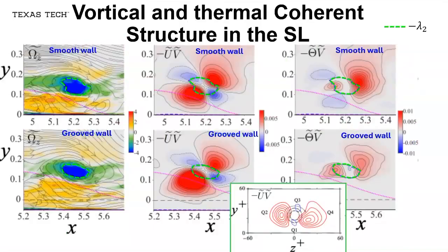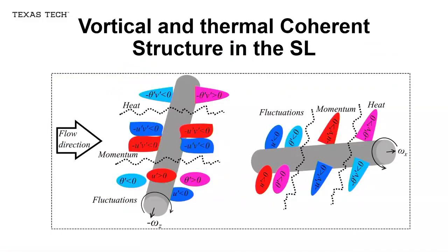And this is like, I took one particular location and made it big, but this is pretty much the same information. Here I'm adding the temperature field. So here I'm also showing the coherent heat flux at one particular x location where we did the eduction of the spanwise rollers. And one interesting thing is, in highly homogeneous flow, the temperature field is very often considered analogous to the velocity. Here we are trying to explain why the velocity and temperature are not comparable to each other anymore.